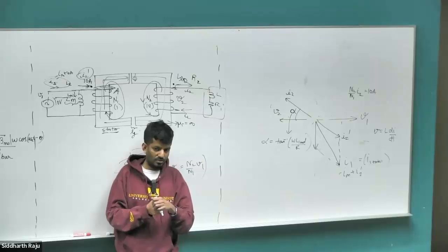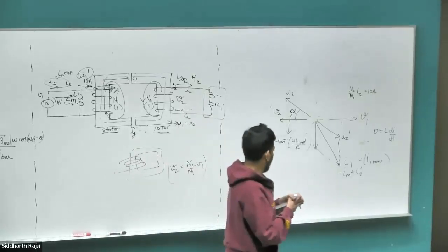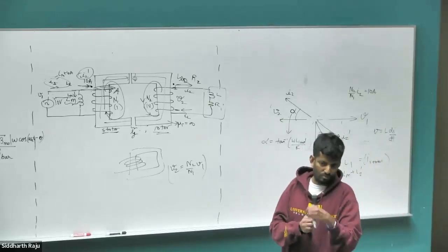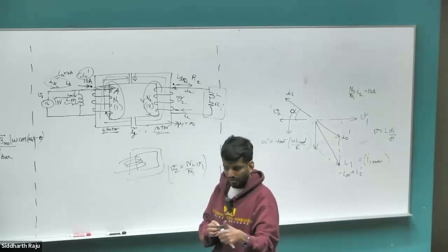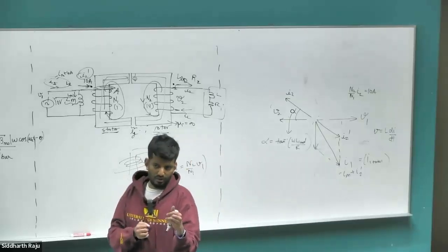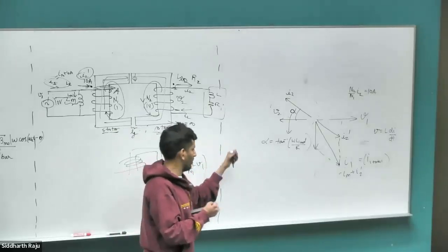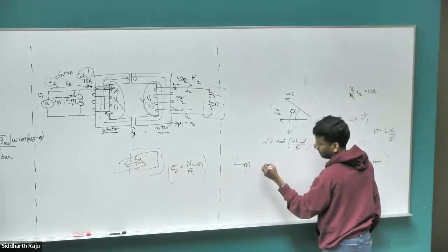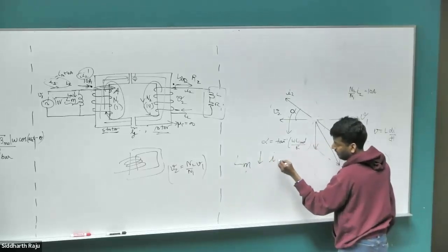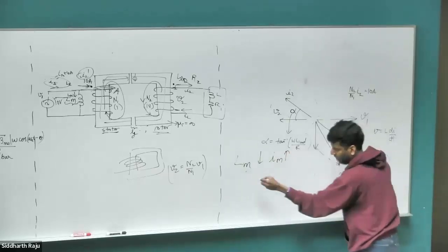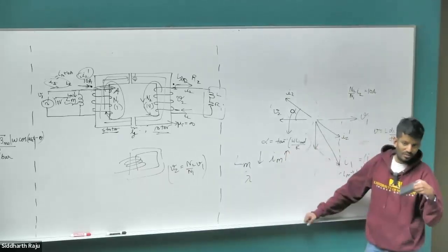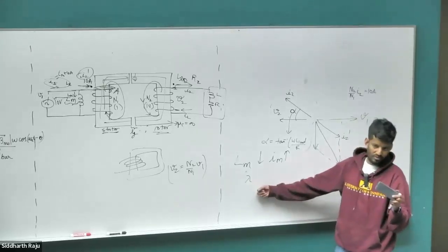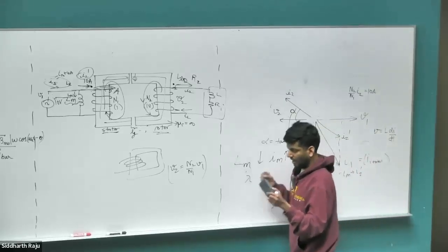Core would saturate eventually? No, you can choose; if your inductance is quite small and you use a high IM current, the flux would still be quite low. Right? You are using a very high IM current because your inductance was quite large. So if your magnetizing inductance is reducing, then you would increase your magnetizing current to compensate, because you want the flux linkage to be the same. Right? So the flux linkage is still the same in both cases. So the core is not saturating before, it's not going to saturate now. So what is the reason we still want to keep the IM very, very low?